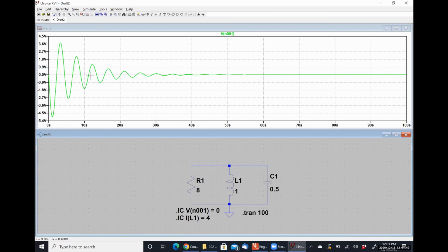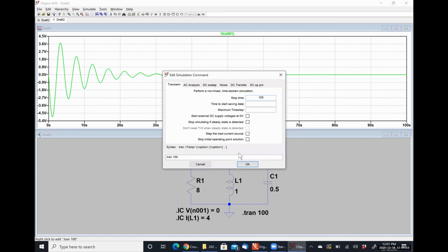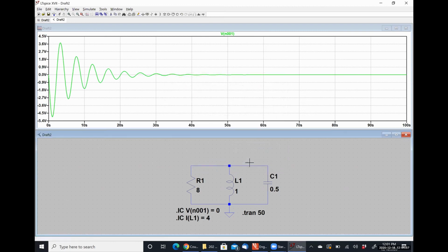Well, no, I don't want to get you in the habit of being lazy. Let's change that to 50. What I'm expecting to see when you submit your graphs is that it settles to its final value with only minimal oscillations. If you gave me a graph between 0 and 10 seconds, it's very obvious that it has not yet settled.